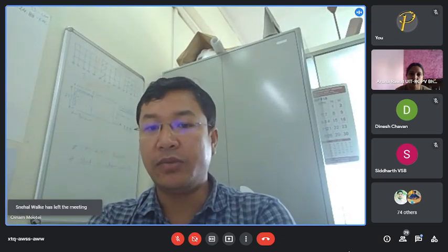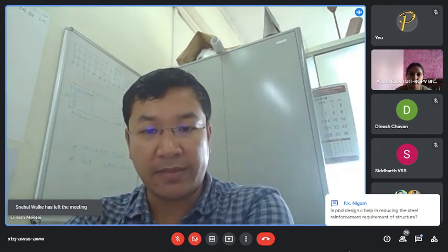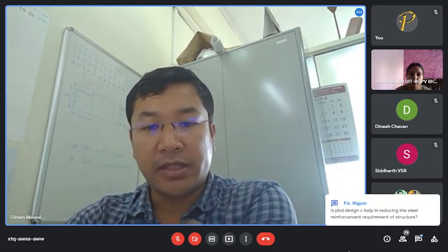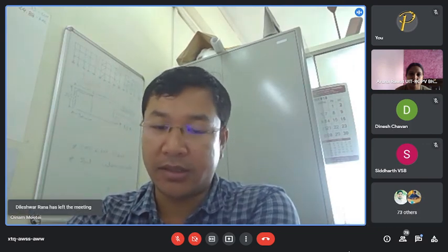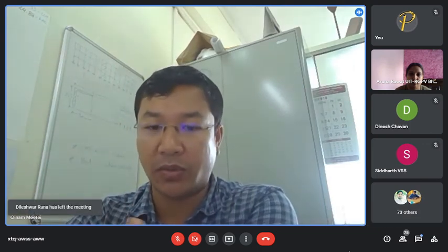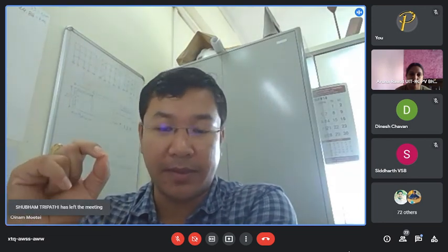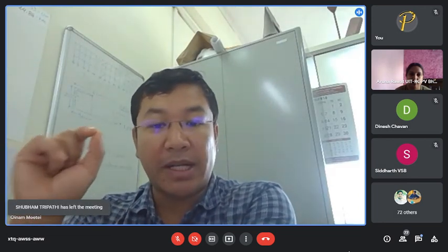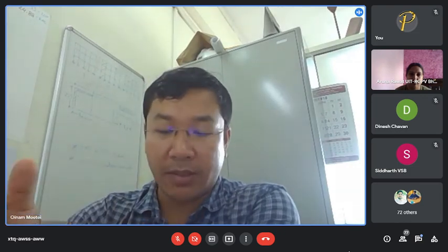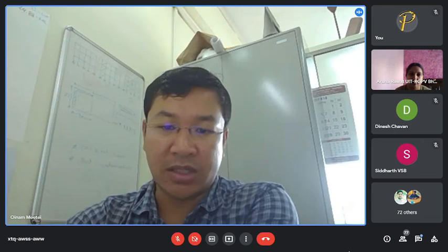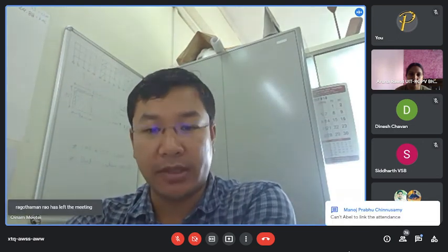But for steel structures with CBF, the concentric braced frame, instead of 5 you can take 6. Or for BRB, you can take 6, maybe 6.5 or 7. But whatever the R value of 8 for Japan, they might be mentioning one particular value. This 8 may be for BRB or some other energy dissipation devices. But I'm sure that 8 is not for reinforced concrete.